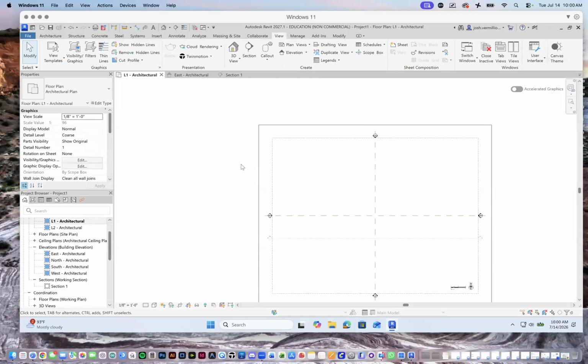It's the same thing for your light vessels. Your light vessels are modeled in Rhino, and we're going to leave them in Rhino and link them up into Revit. So if you need to make a change to your light vessel, you go back into Rhino and make the change. Next time you open things up in Revit, you'll see the updates. And then there's the rest of the building that we're going to model in Revit.